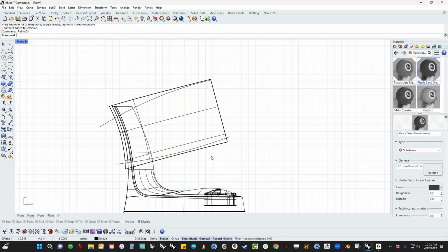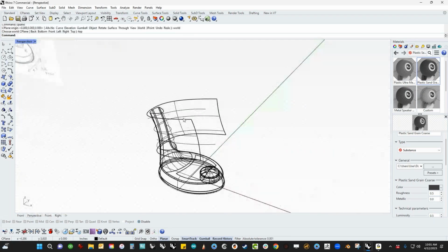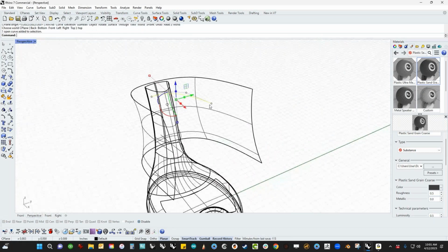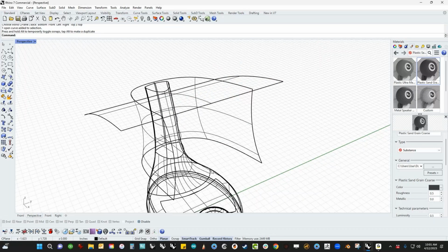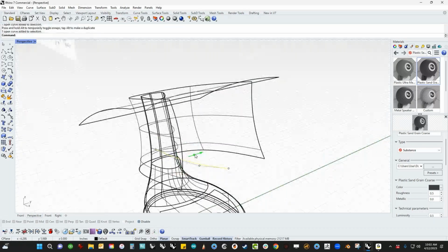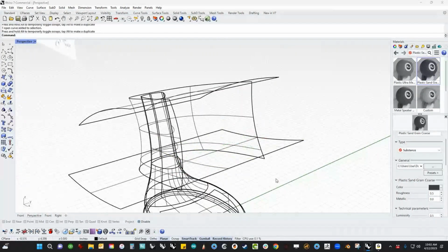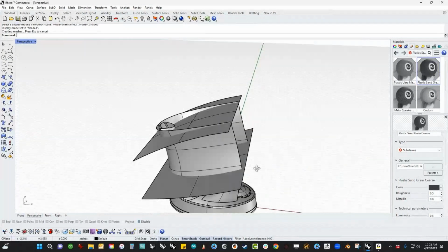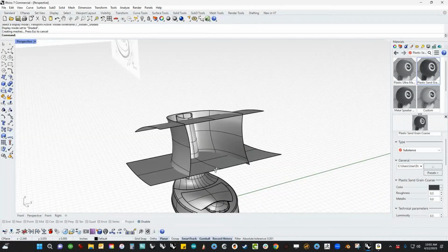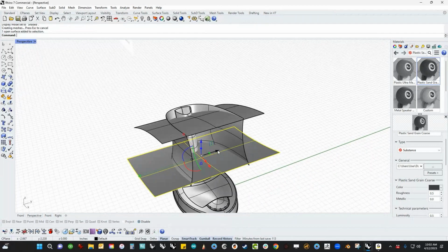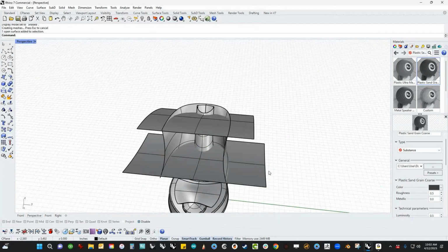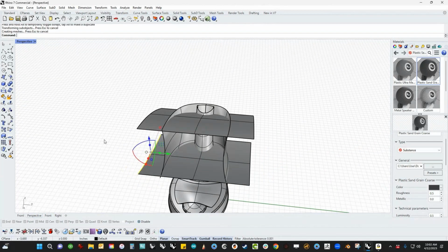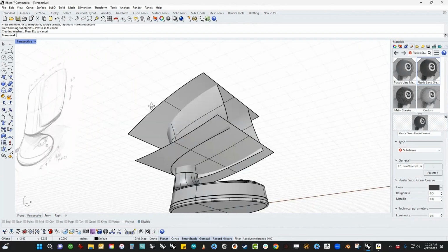And so now what we can do is grab this. I can drag the extrude dot, hold down shift, do the same thing down here, drag the extrude dot, hold down shift to go in both directions. And we end up with this, right? Now, it would be nice if these both were the same length. So I'm going to Control Shift click the edge, and drag it back and then use snappy dragging to get those about the same width.